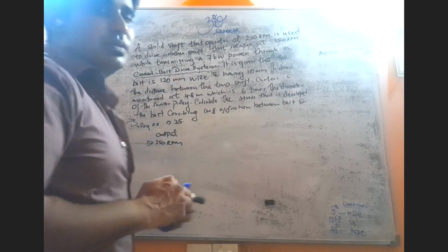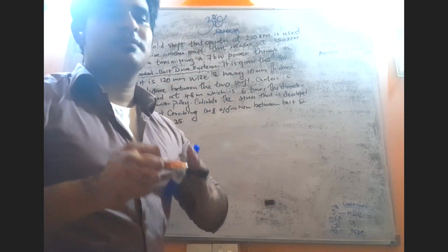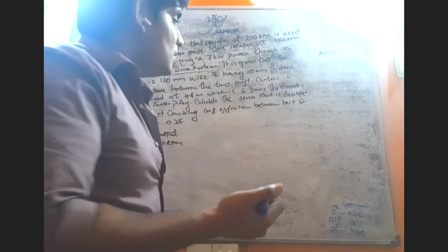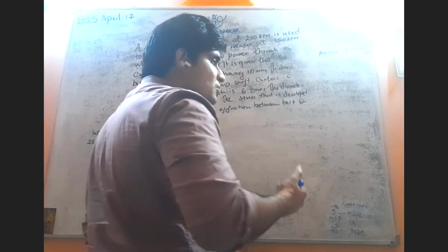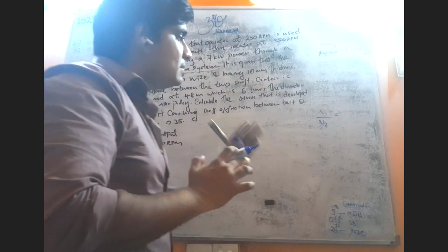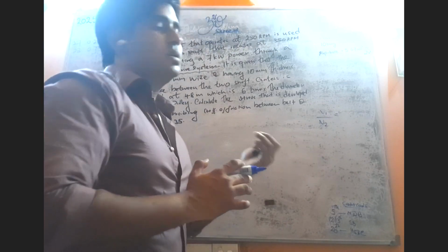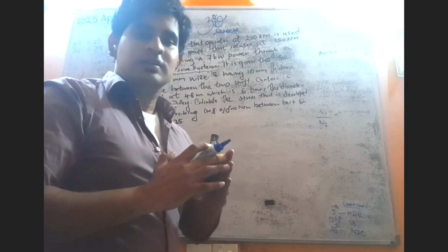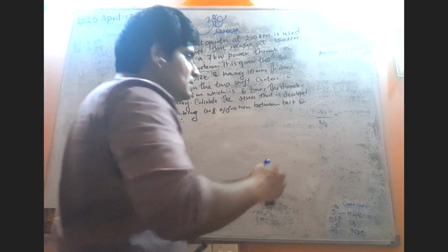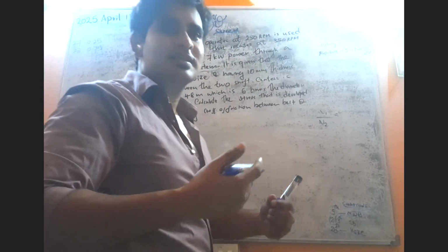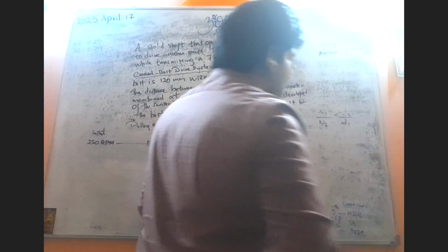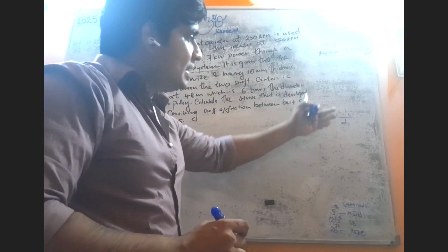And also we know that when we are solving this type of question, there are certain basic equations that we must know. One equation is the ratio of the RPMs. Let's call it N1 divided by N2. Sometimes N1 can be the input RPM or whatever. Just for remembering purposes, let's say N1 divided by N2 equals what? That equals the ratio of the diameters the other way around, so we can call it D2 divided by D1. N1 divided by N2 equals D2 divided by D1, and that is one thing.